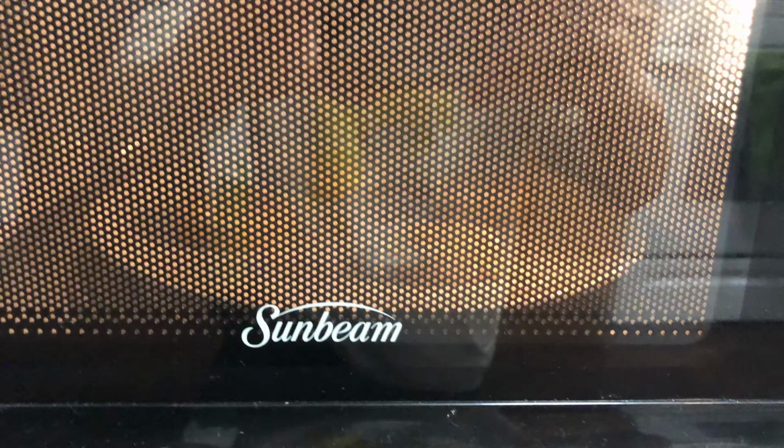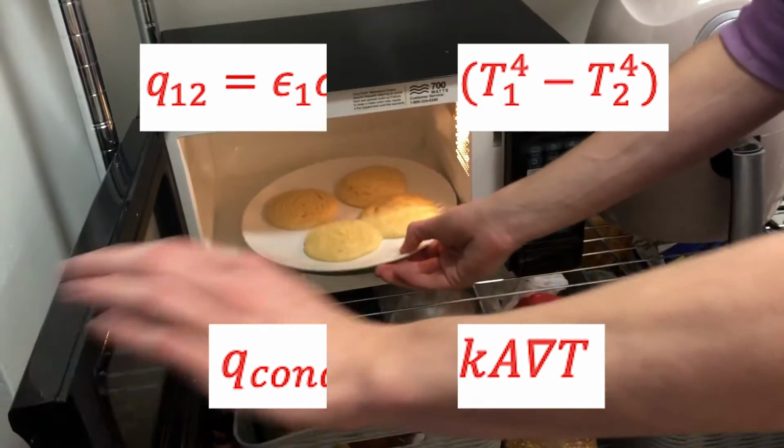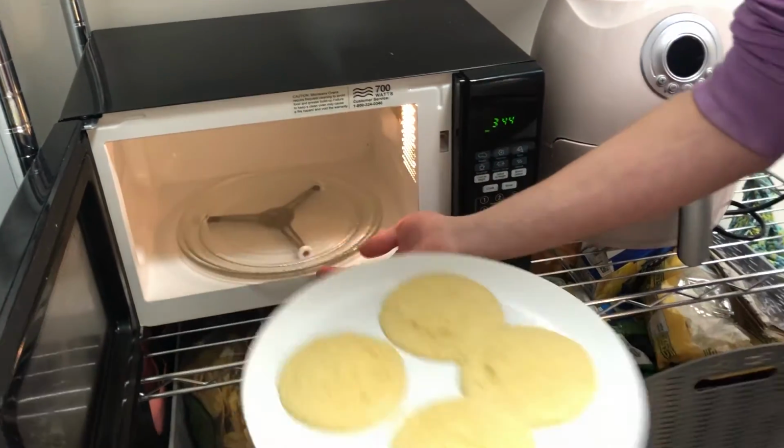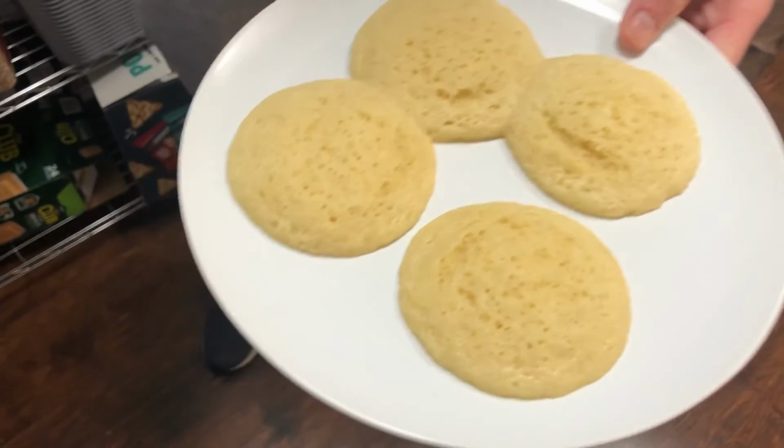Radiation occurs when energy is transmitted in the form of waves into a medium. The exteriors of thicker foods are cooked directly by the radiation provided, but the insides receive the majority of their heat from the conduction through the hot outer surface. The heat transfer of a microwave is governed mainly by the Stefan-Boltzmann law and Fourier's law of conduction. Water molecules that vaporize in the microwave contribute both free and forced convection, but these sources of heat transfer are considered minuscule compared to radiation and conduction.